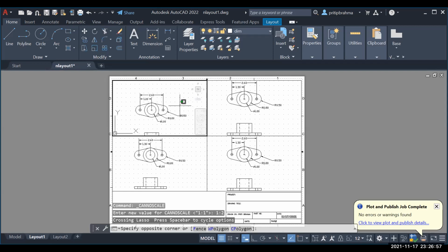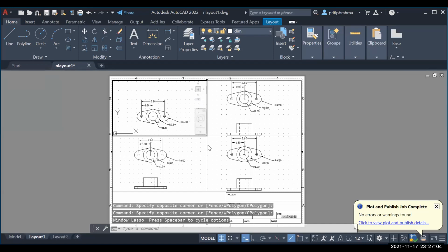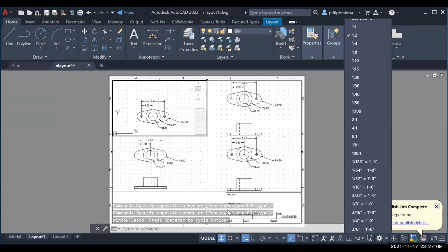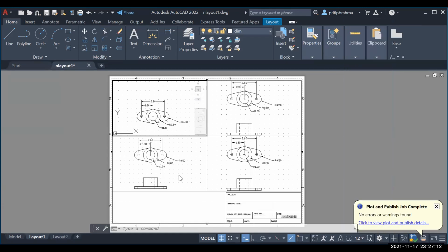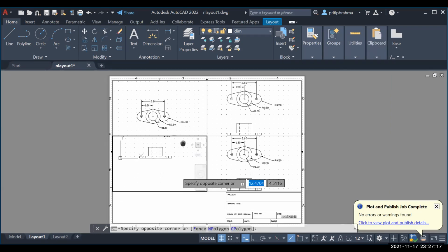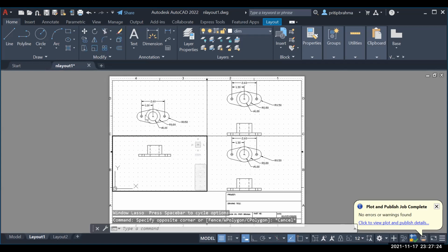Yeah, of course. Double click. So you first double click in the block you want to be in. Okay, so I'm in this block. And then you go down here to this arrow that gives you all of those. Note that you probably want each window to be the same scale because otherwise your views aren't going to align properly, right? So the only way the edges of this meet with the edges of this is if it's the same scale. So we kind of need to have the same scale anyways.